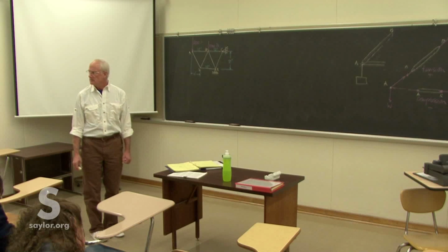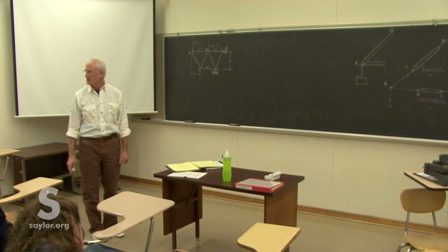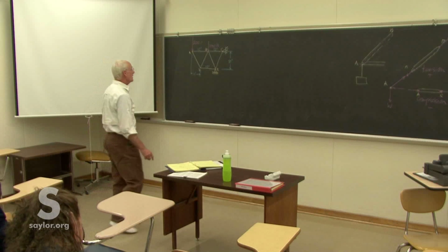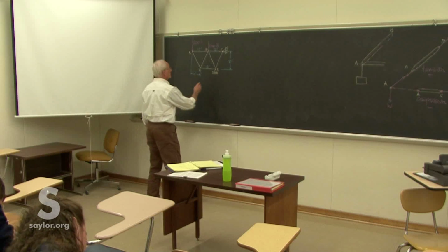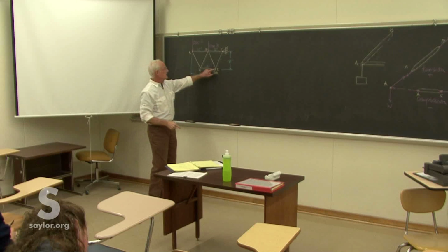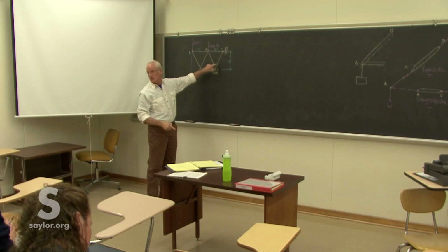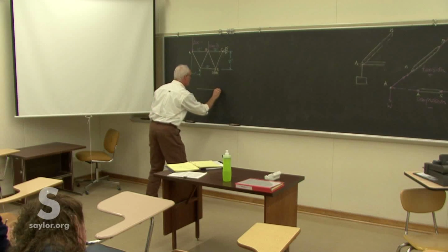First step. First step, look at where I listed the steps. What did I say? Free body diagram? Yeah, free body diagram of the whole structure, entire structure, because we need to find out what these reaction forces are, because that's going to determine the forces in each of the members. So we'll keep it simple.